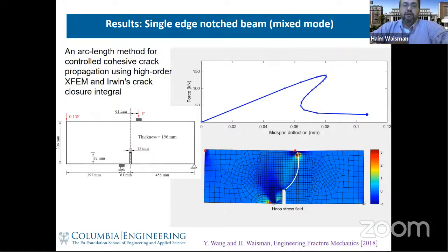And with the cubic degradation function, people are trying to match the linear elastic response of the material better, in the sense that the quadratic one will curve or bend very quickly, while the cubic one will go more straight, right, and reach a higher peak or a higher strength. So there are some famous papers that discuss it, but essentially, I think that the phase field comes from a mathematical point of view, essentially.